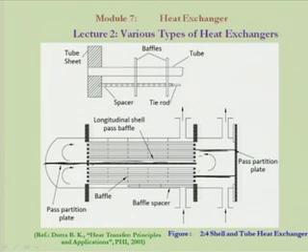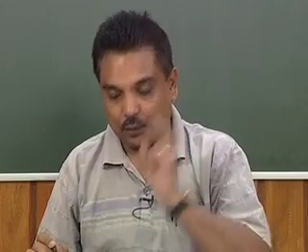These are all tube side partition plates. Also in the shell side there is a partition plate. The shell side partition plate will be horizontal and run longitudinally all through, so that no fluid from one side of the partition can move to the other side. Therefore, the number of passes in the shell side will be 2, so shell side fluid will pass through this heat exchanger twice.